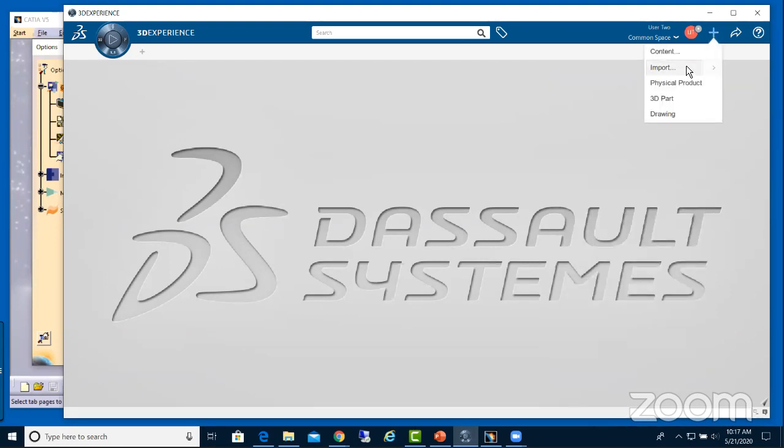After that, we have import. It allows you to import a large number of different types of files. When I select that button, the arrow to the right, this allows me to bring in the CATIA files from CATIA V5. So I can actually open up and it'll bring in any of the CATIA V5 type files into 3DEXPERIENCE. Physical product, 3D part, and drawing basically act just like content. I can open up an instant new part or product right from here.